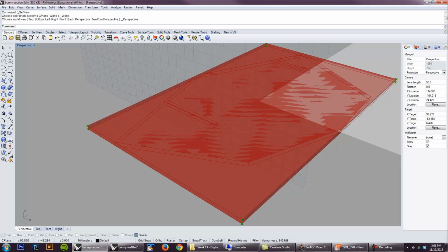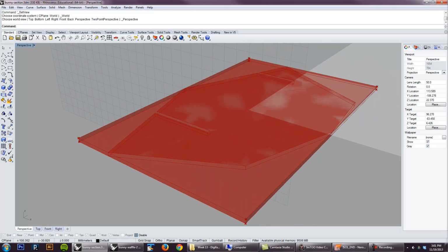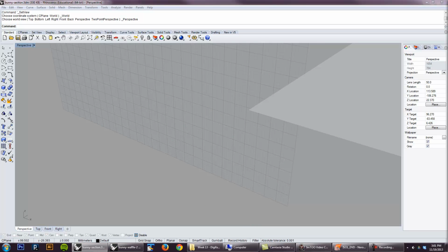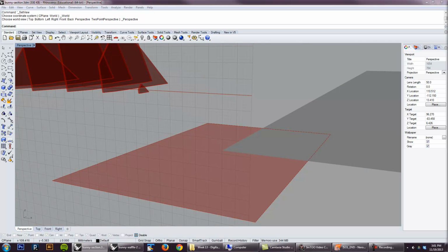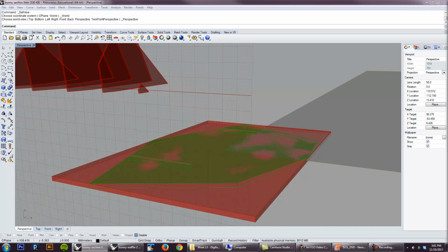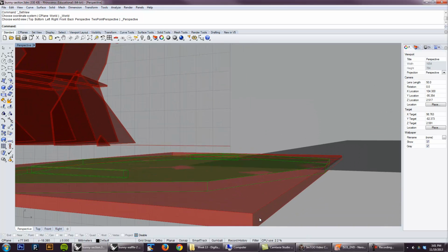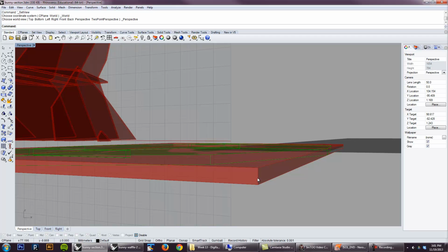Okay, from the box corners, I'm going to take the first 4 corners and use those as the basis of a 4-point surface. If I plug in the first 4 corners, then I get a surface that's perfectly sized to the box. Then I need to move that surface. So I want to use a distance component, and using the first and the 5th point on the box, A and E, find that distance, find half of that distance, and then move my plane half of that distance in the z-axis.